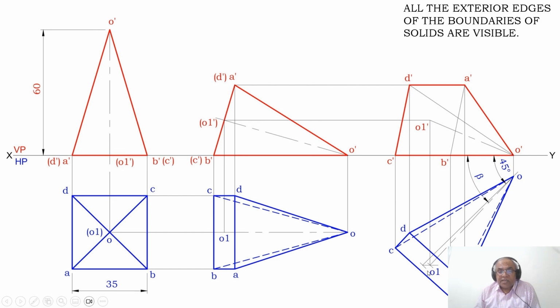Again you come to this extended line here with the same center. You cut an arc on this side and also from this side, and you mark these points as A, B, C, D. And you join all these lines, including the dotted lines, the visible lines and the axis, as the same. You rewrite the same sketch.